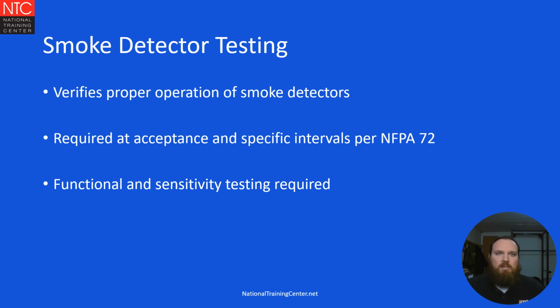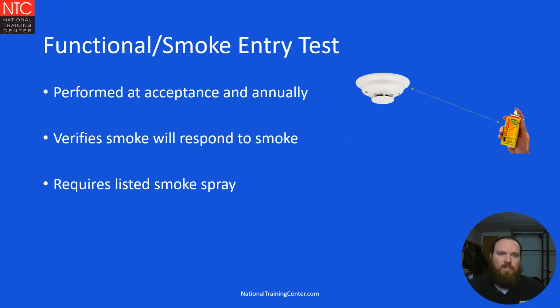All devices have to be tested during acceptance. Smoke detectors, no different from that. And there's going to be specific intervals per NFPA 72 at which smoke detectors are going to be tested. Things that we're going to be looking at testing with smoke detectors: a functional test to ensure that it is operational, as well as sensitivity testing. These are two separate things.